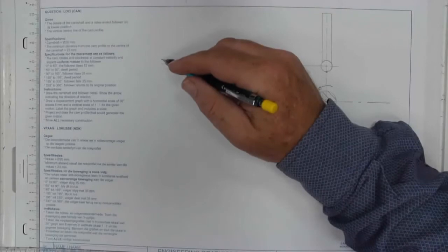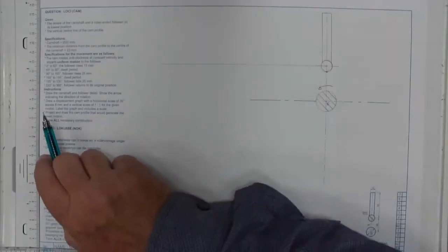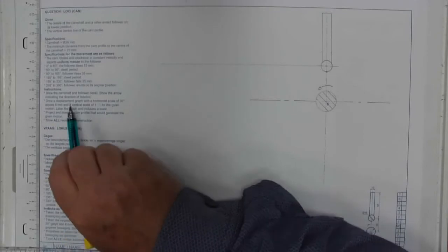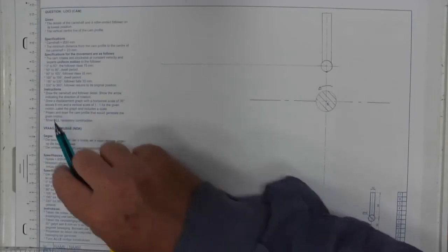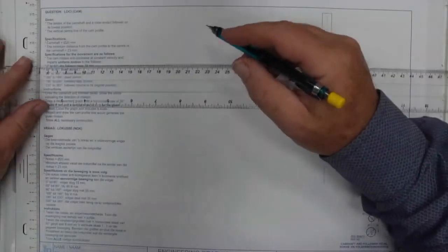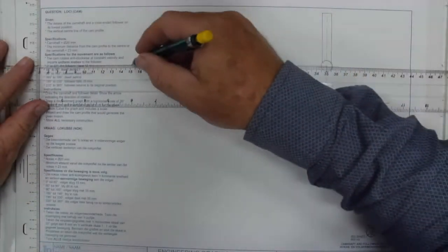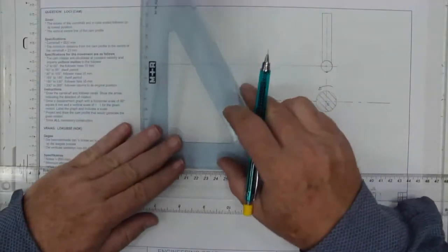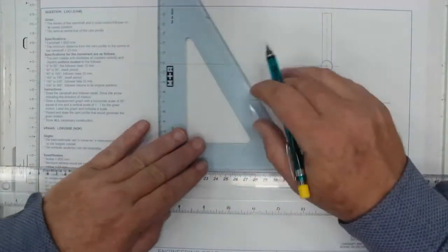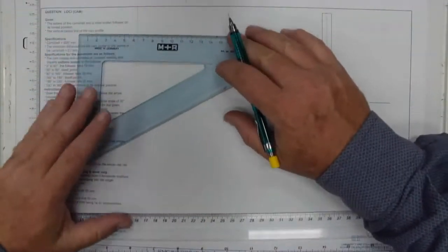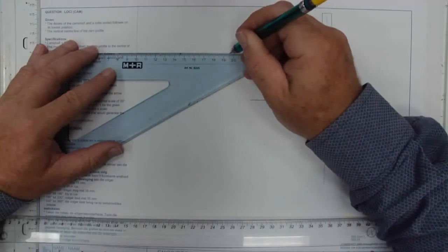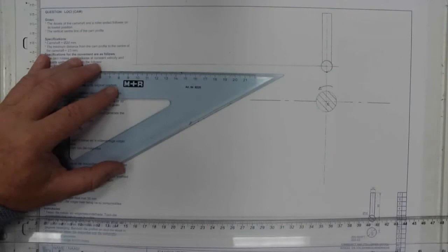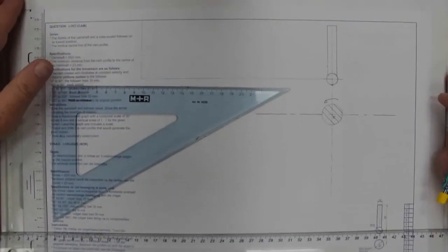Now let's go about drawing the graph. What information do they give us about the graph? They say use a horizontal scale of 30 degrees equals 8 millimeters. So we need 12 measurements of 8, which means we need an overall distance of 96. So just to make sure I'm not going to crash into that, I'll start relatively close to where my printing is and mark off my distance of 96, and divide that up into my equal measurements of 8 millimeters.